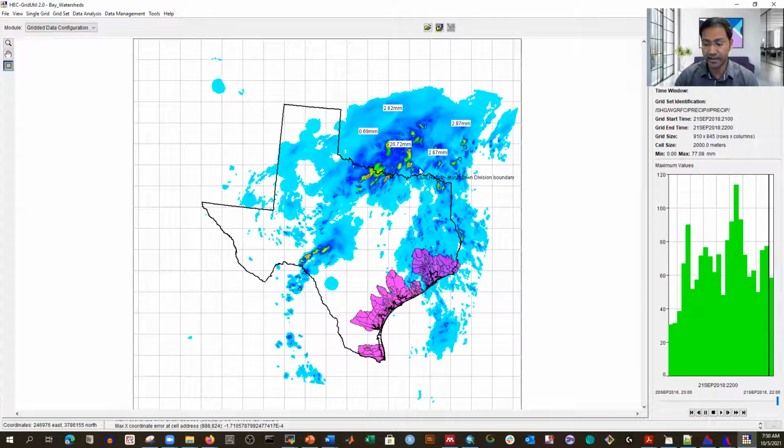And if you also have the output of HEC-HMS model, or output from the HEC-RAS model, whatever the output you have, if you have the output as a .dss, and you want to plot or display it spatially, or plot the flood inundation map from the HEC-RAS 2D model, or see the display of runoff from the gridded model developed in HEC-HMS, because the outputs are .dss. So once you have the .dss output or input, you can display here.